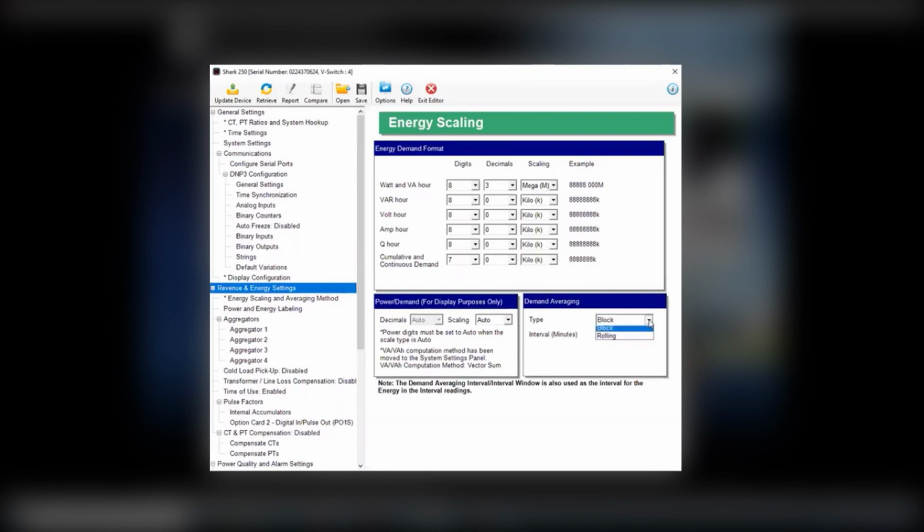If you're storing energy in a rolling window, rolling or sliding window is a term that people use a lot, you would basically have data that's being sampled at a particular rate. So in this particular case, we have a 15-minute interval. We want, let's say, 3 sub-intervals. Let's make that 5-minute intervals, and we want a 50-minute block or 50-minute interval. The advantage of having rolling is that the rolling method of demand provides the highest demand that you could have.